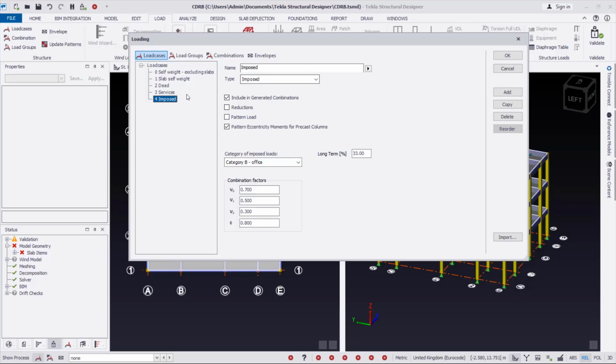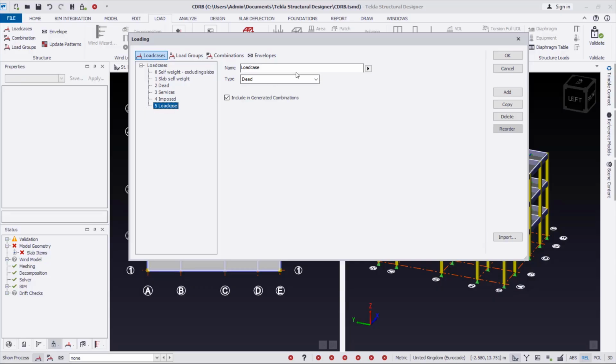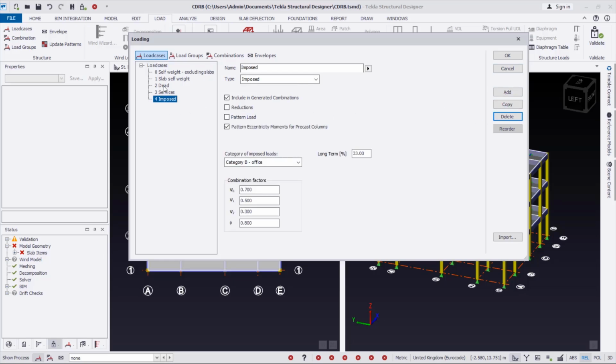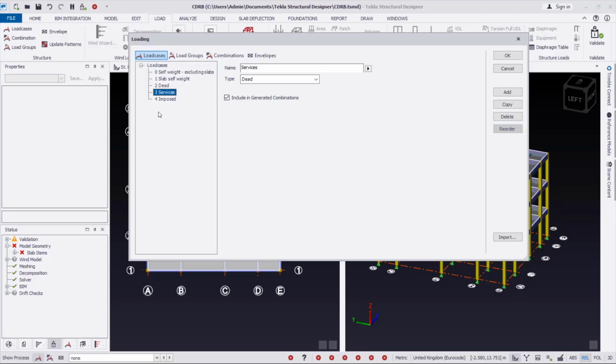All right, so if I want to create an additional load, whether an additional imposed load and the rest of that, or live load, you just have to add from here. You can see load case here, over here, give it a name, and then the type and the purpose of it, you can also select it from here. Okay, so I can also delete by selecting it and then clicking on delete from here. All right, so we go by this default.